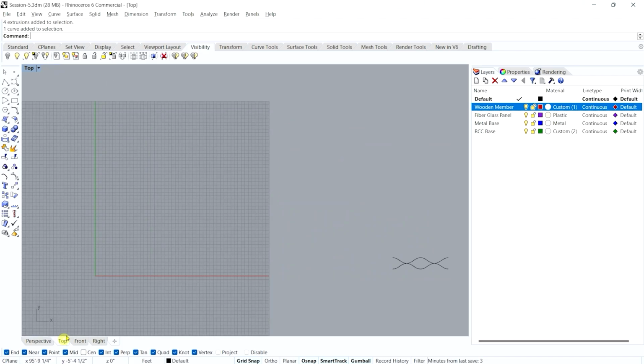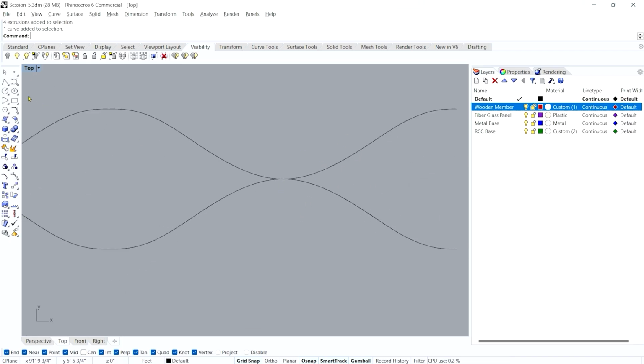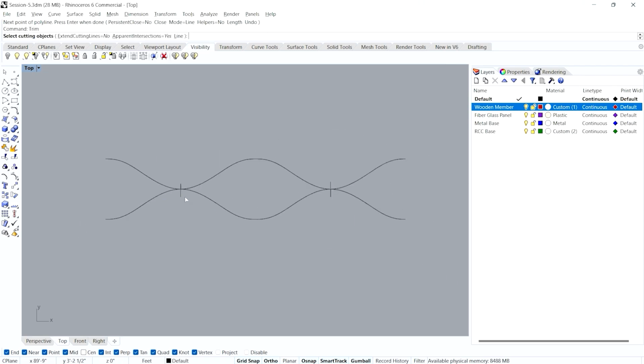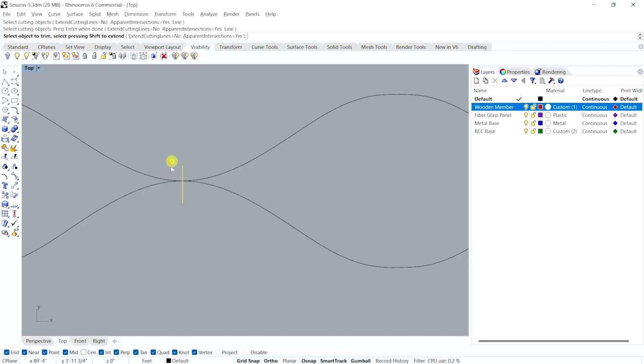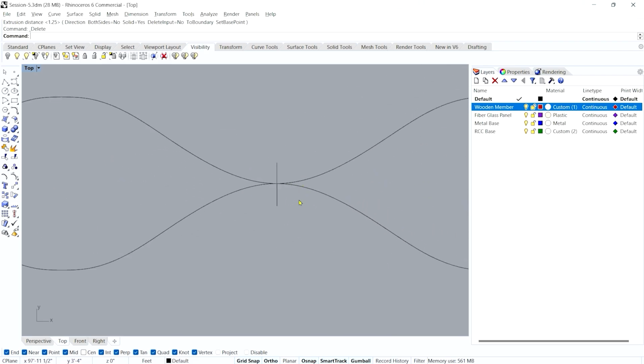Next, I want to take out this point also, take out these lines also. I don't want them. Use the polyline command and find the intersection. Yes, this is the intersection. I will draw lines here on my ortho. Same way I will find the intersection. Repeat the command, right click, intersection, draw the line, and then I will use trim command to chip off the remaining portion, and delete those lines. You can see perfectly I've got the intersection lines, and I will repeat here.